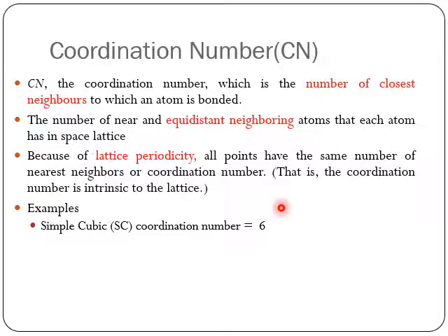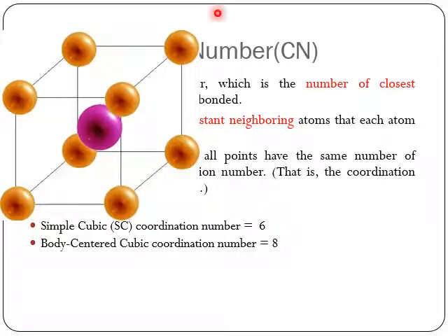So if you take the next one, that is a body center. This is how exactly a body center looks like. This is the atom which is at the center of a body, and it is surrounded by 8 atoms, 4 here and 4 at the bottom. It is nothing but like a ball which is kept inside a box at the center. So 8 corners, so there will be 8 atoms. That is number 8. Okay, this is simple to understand.